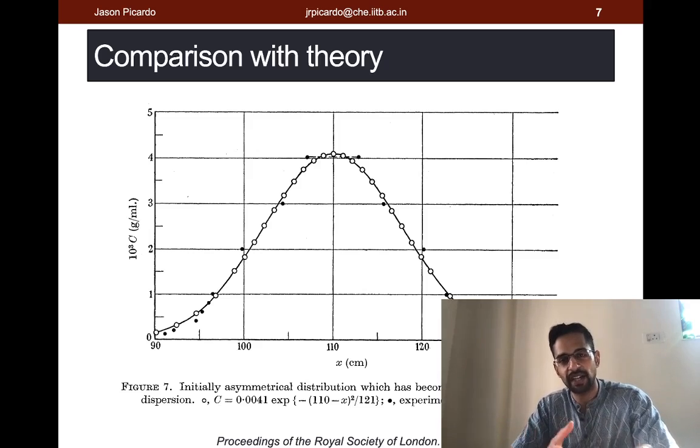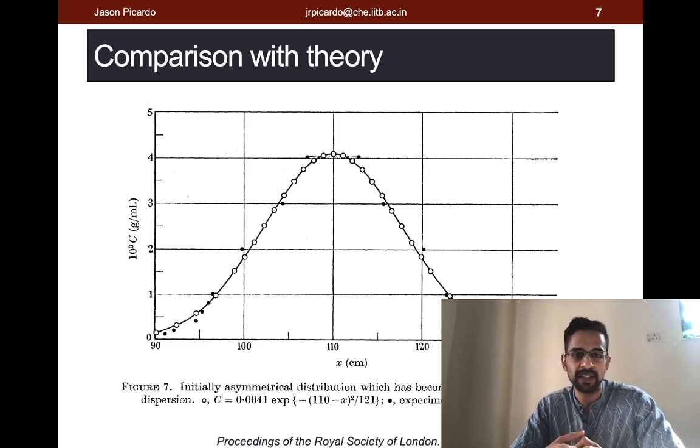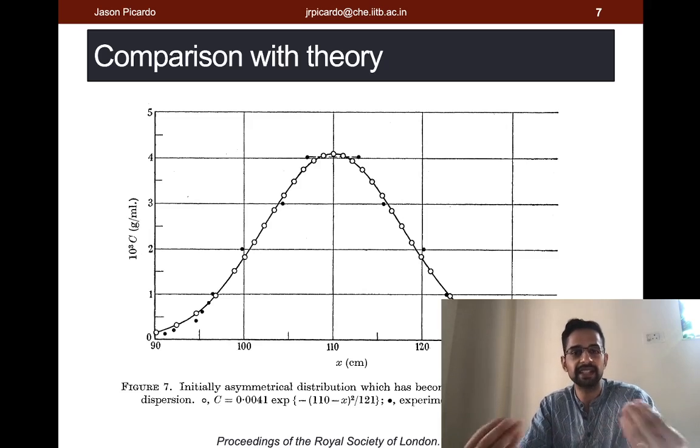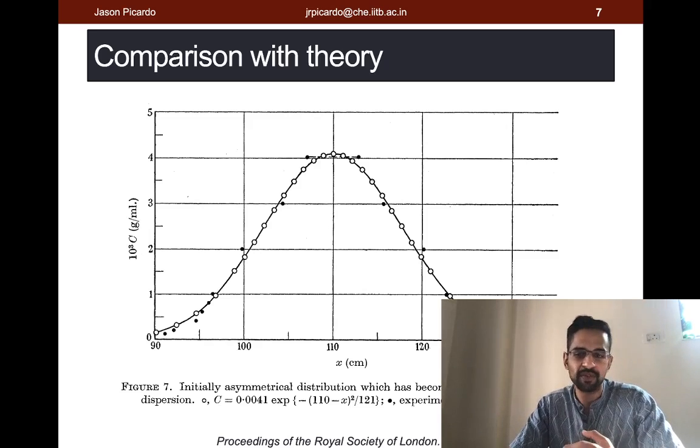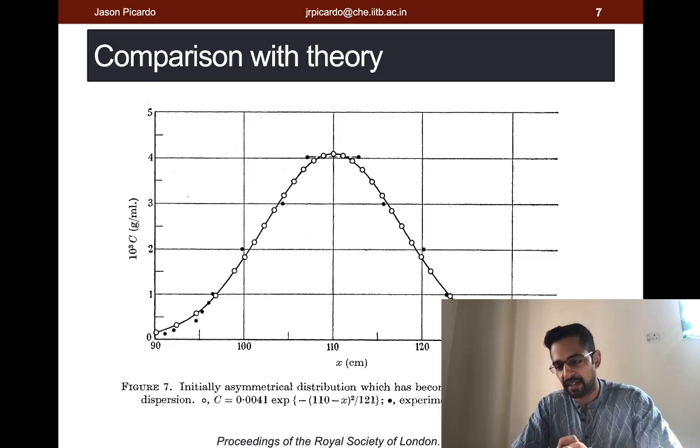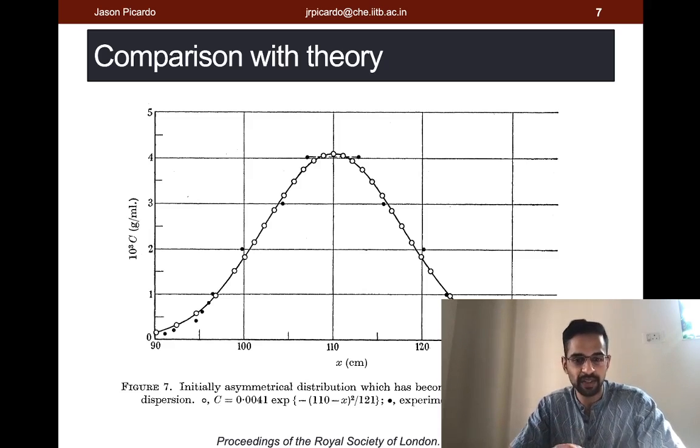And once we do that, we have this approximate relationship. We can then substitute it into the averaged equation we obtained by averaging out the original PDE, and then get a model that directly describes the average concentration as a function of the axial distance and time. More broadly, this is an example of what's known as order reduction techniques, or reduced order modeling, or low dimensional modeling. And this is a very powerful, increasingly important method in today's engineering.